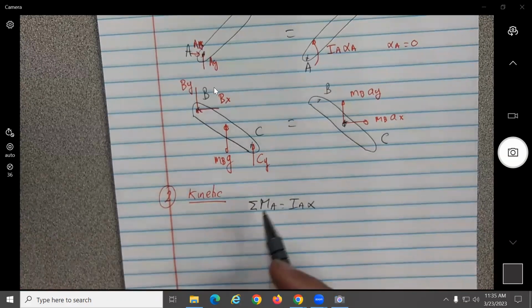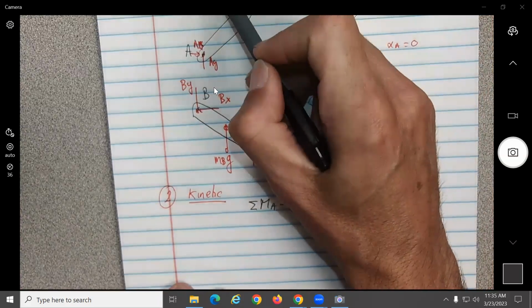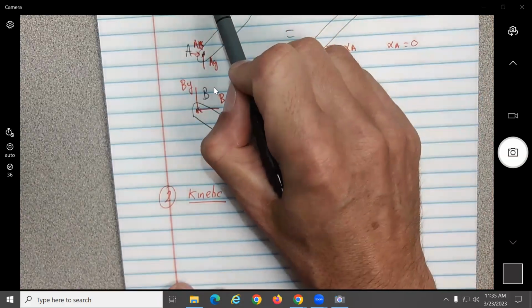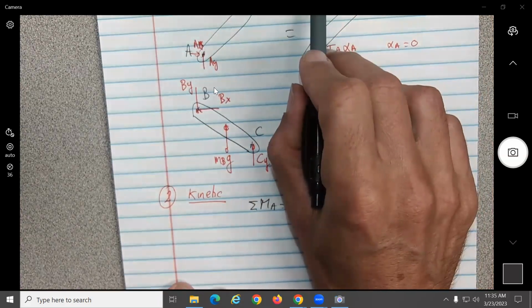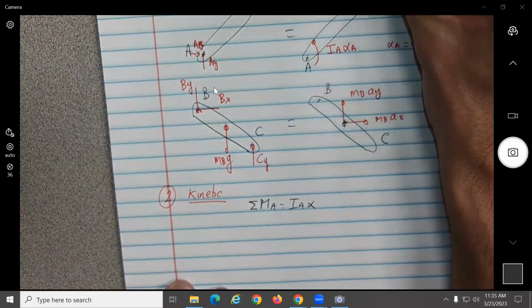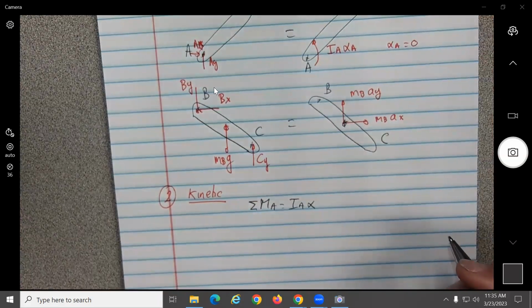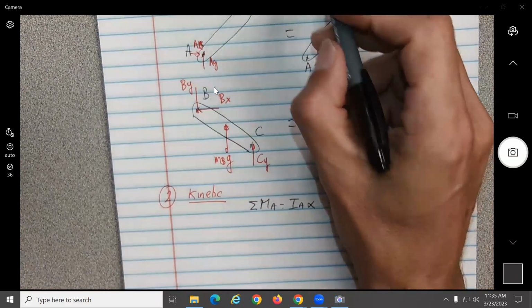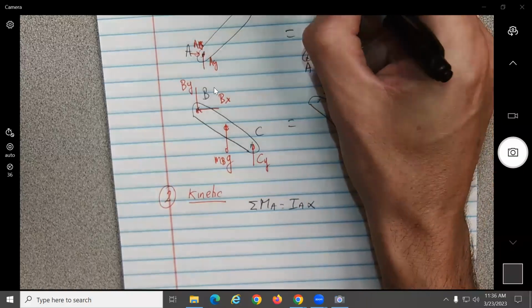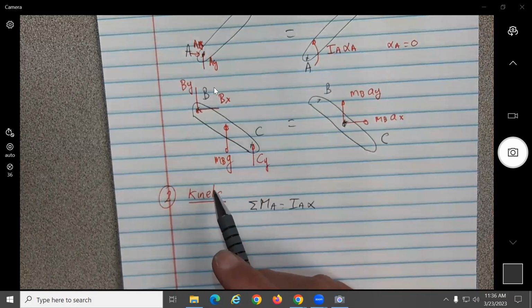This problem, then after you do this, write down the equations. What you're going to have to do, you're going to find the velocity of B from point A, where you will know that the velocity of A is 0, no? But what would you know about the velocity of C? You will only have one on the x direction, no? So what would be the two unknowns? We have two equations, no? One unknown will be VCy, and the other one will be omega BC. I think that was your question, no? Basically. Yeah.